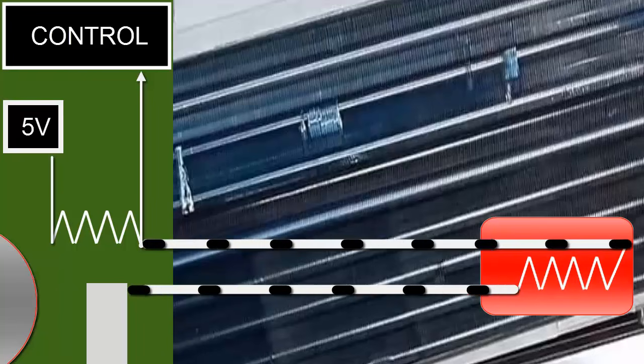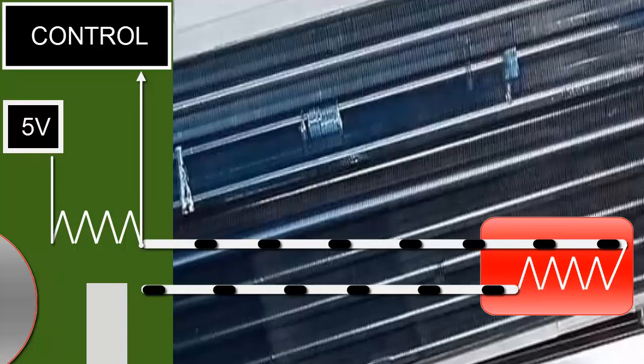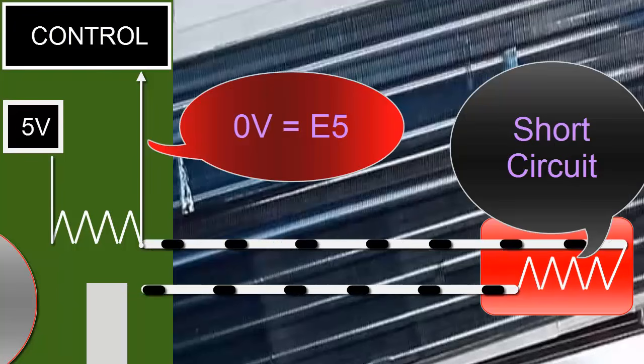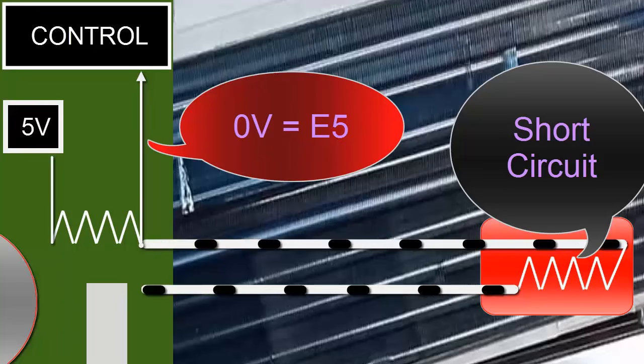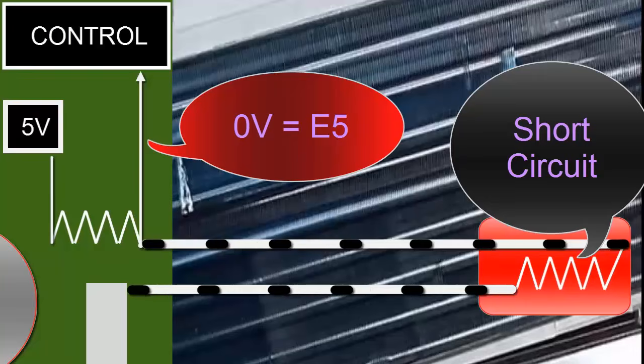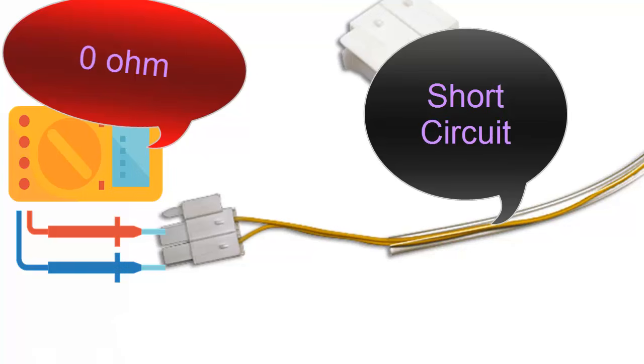10. Another related problem is if the sensor is short-circuited. In this case, the sensor's resistance is so low that all the voltage is lost in the internal electrical resistance of the card, triggering the E5 error. The sensor's short circuit can be diagnosed using a multimeter, and when disconnecting the sensor, the reading should never be 0.